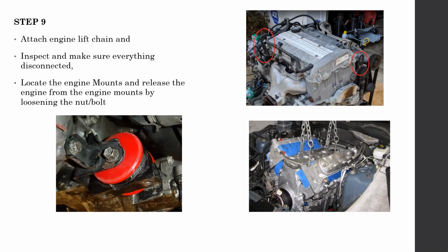In such cases, you have to use additional hardware as shown in the second image. You can see there's a metal plate and two L-shaped components fixed into the engine block. These are additional components that have been attached to the engine so it can be lifted. Since this is a V-shaped engine, there's no other place to put the bolts. That's why they have to use something like this.